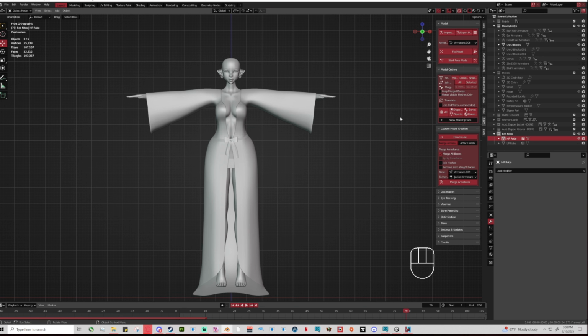And then whenever you bake it, it's basically like printing the shadows from the high poly version onto the low poly version, which is how so many asset creators, myself included, can give you a really low poly outfit, 10k polys or lower, but it has all these details of folds and it looks like there's shadows on there even though it's flat as can be. So that's what we're going to prepare for.